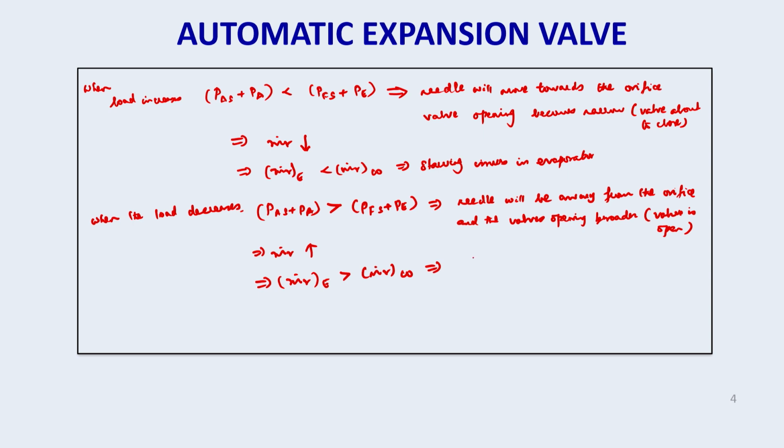So, under this condition, the evaporator is flooded with liquid refrigerant. Here also, critical charge has to be used to avoid starving issues and flooding issues in the evaporator.